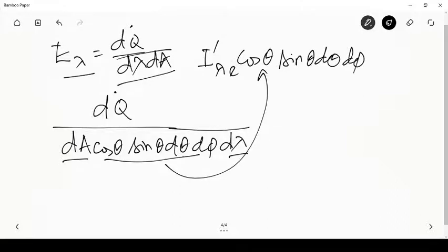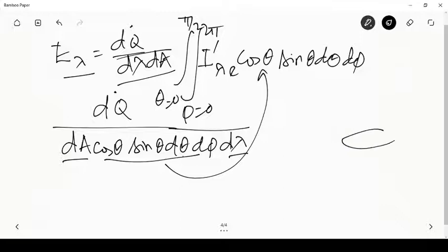And that gets integrated over theta equal to 0 to pi by 2 and phi equal to 0 to 2 pi. So basically, if I take the radiation intensity and integrate it over the entire hemisphere, so if I have the radiation intensity going in one particular direction as I prime lambda E, if I integrate this radiation intensity over the entire phi range and the entire theta range, so that it covers this entire hemisphere, and because the projection direction is also rotating around the whole thing, this cos theta would also get absorbed there.